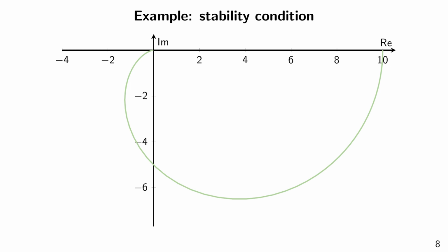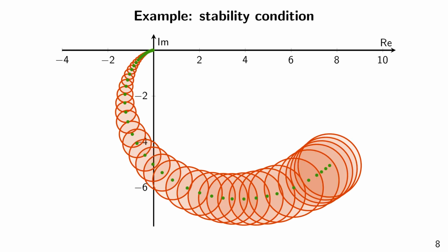This is the Nyquist diagram of the nominal system for non-negative frequencies. We sample this frequency response over a grid of frequencies that are rational fractions of pi. Due to the uncertainty, the response of the system expands to circles at each frequency like this. Let us take a closer look at this area, because this is where the critical frequencies are.